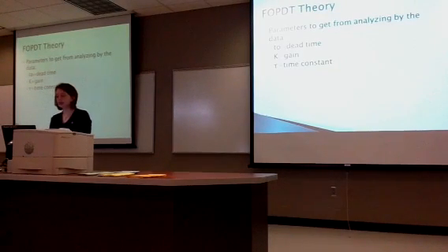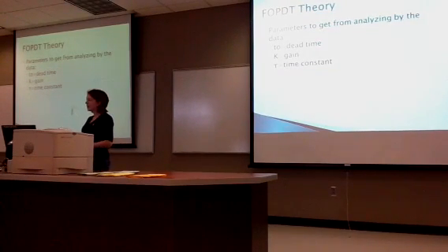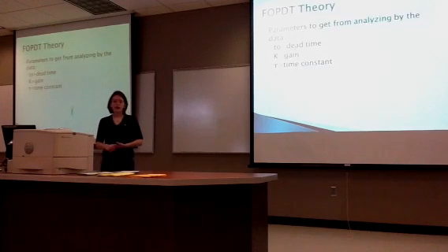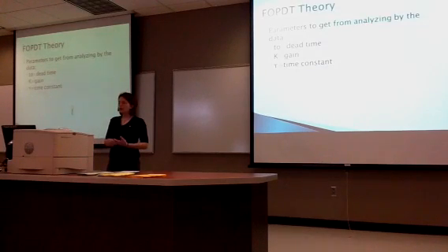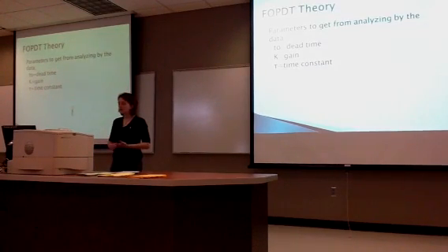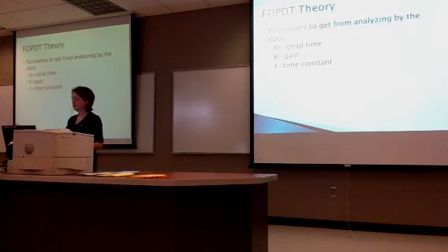First order plus dead time theory, you get that by analyzing the step up and step down graphs. And from the graph, you get the dead time, the gain of the system, and the time constant of the system.